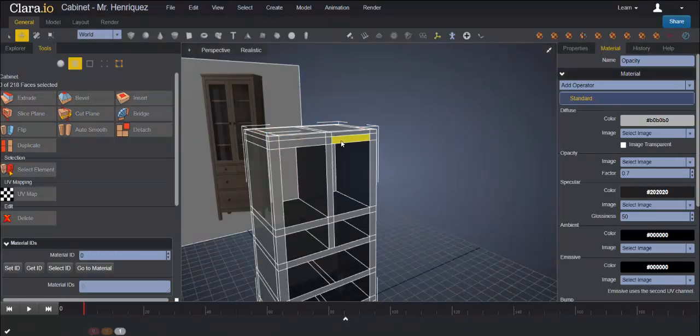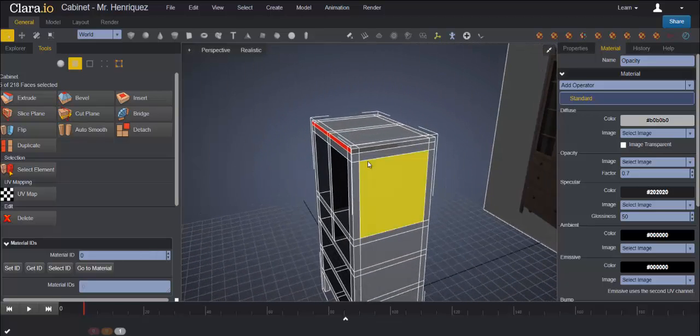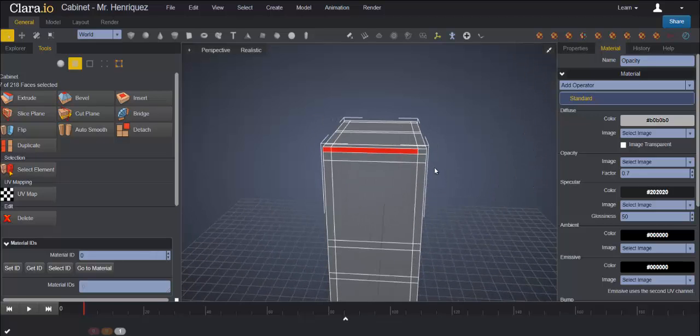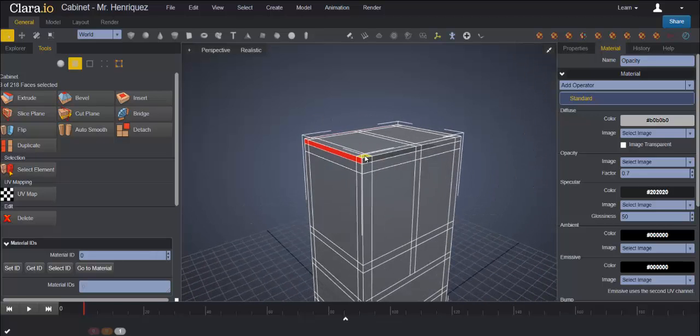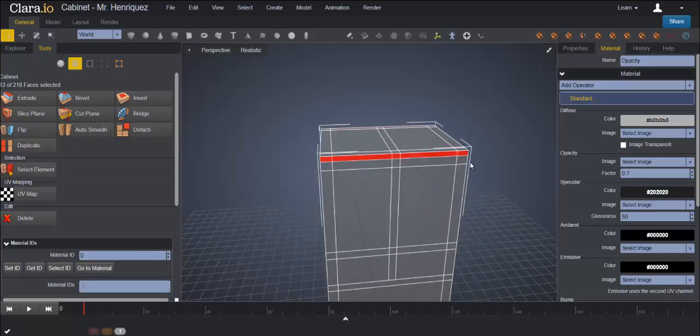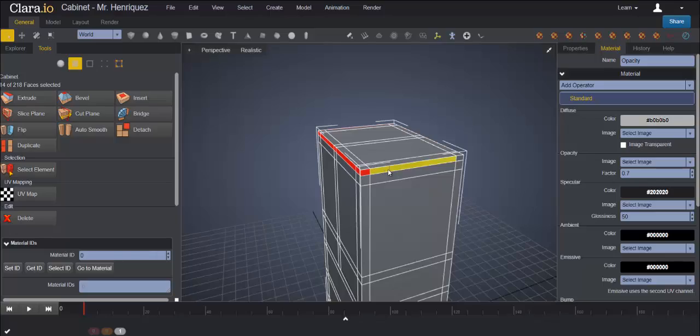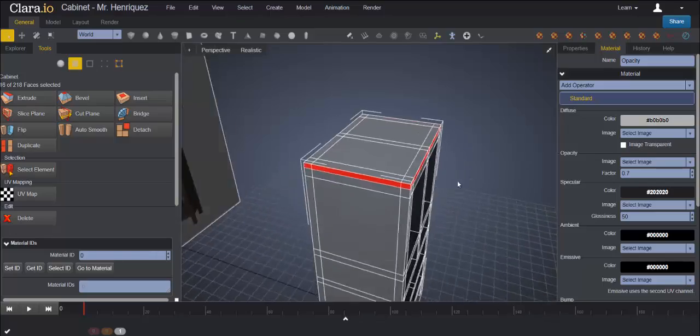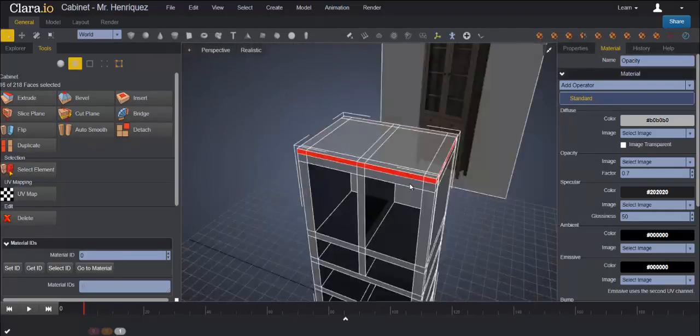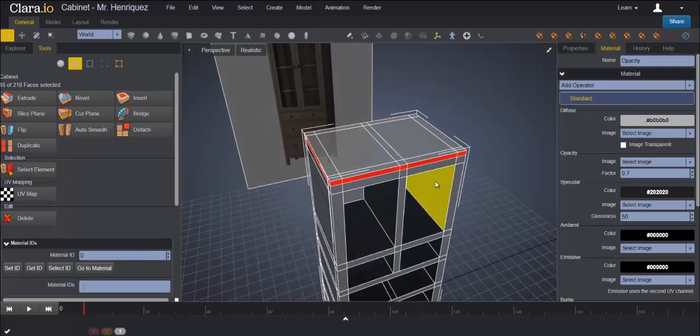Now I'm going to select the side faces for that extrusion. So I'll click on one and then start selecting the other ones by holding Control key as you click on the other edges. And we're just selecting the ones all the way around. Don't select anything else. So be careful as you're clicking each of the faces. And then just rotate it, make sure nothing else got selected, and go ahead and press extrude.